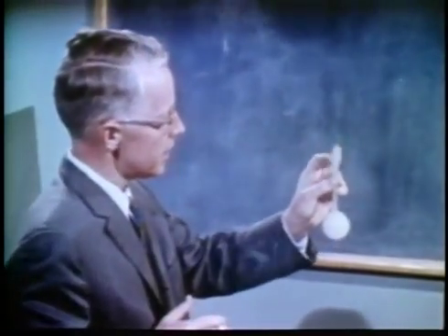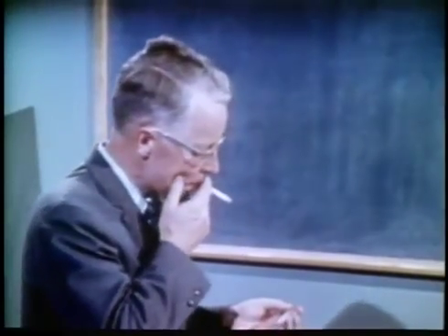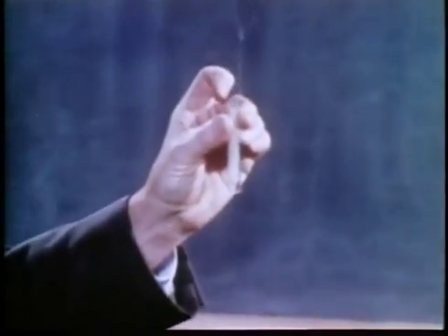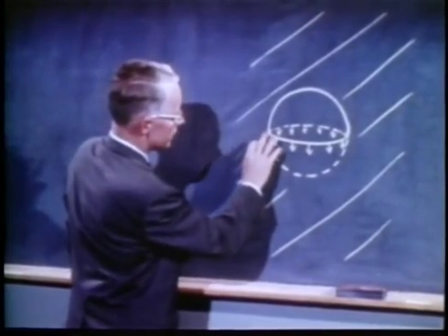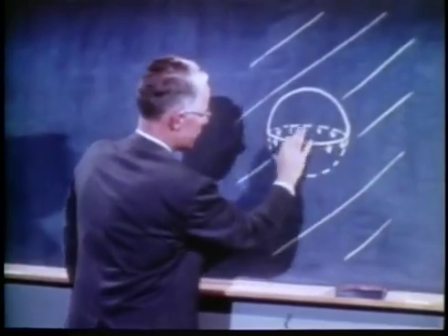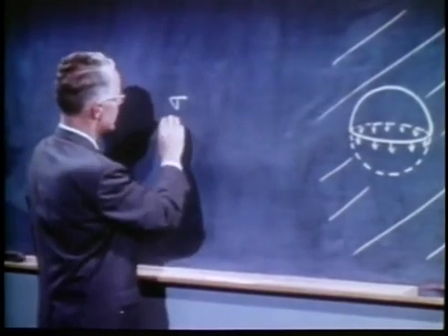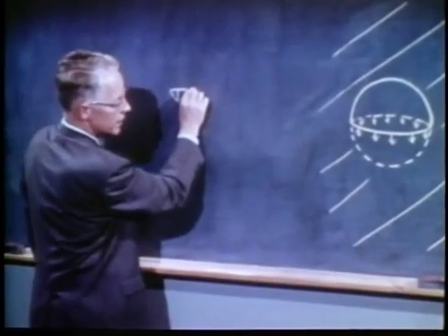the higher pressure inside forces the smoke out. The energy of the surface becomes converted to the kinetic energy of the smoke jet. We can calculate this higher pressure. Consider the upper half of a gas bubble immersed in a liquid. Surface tension will pull down all around the equator with the total force equaling the surface tension expressed as force per unit length times the length of the circumference.